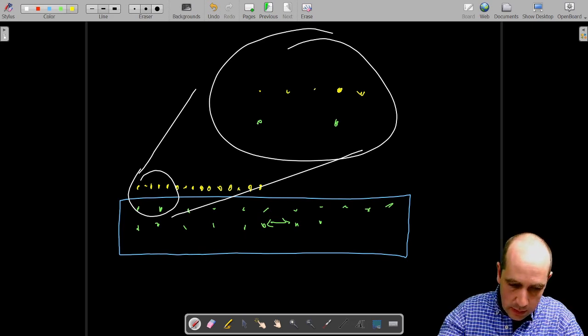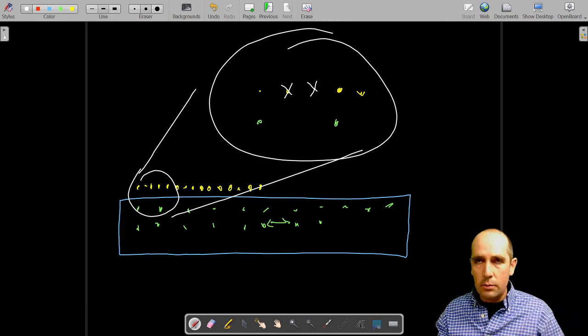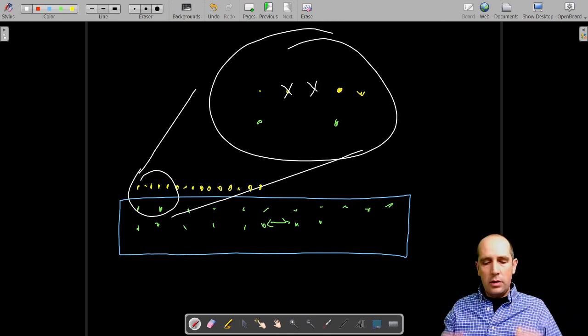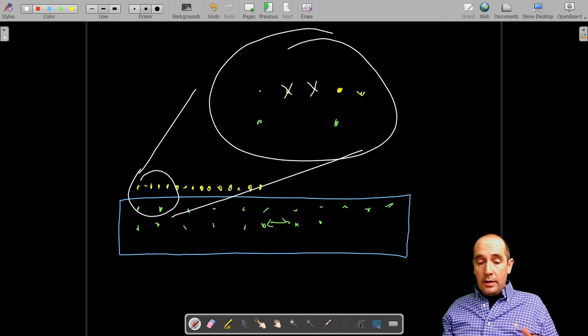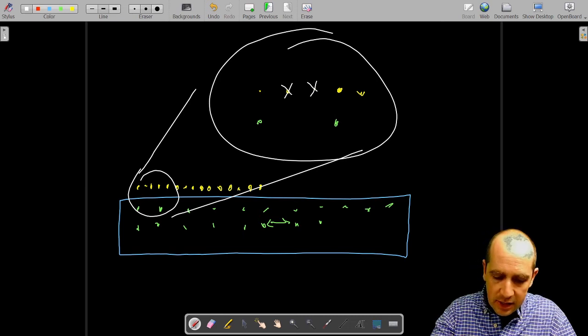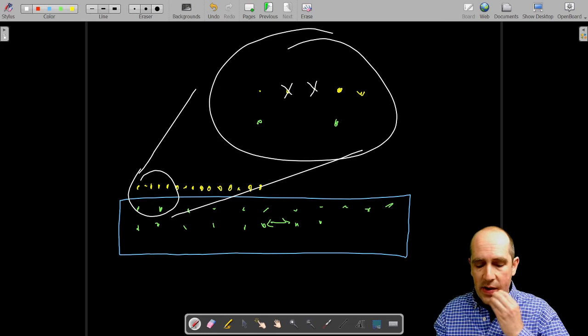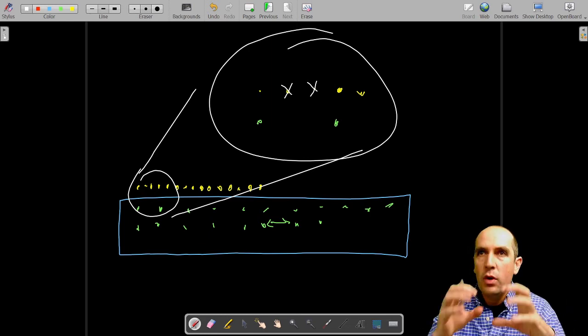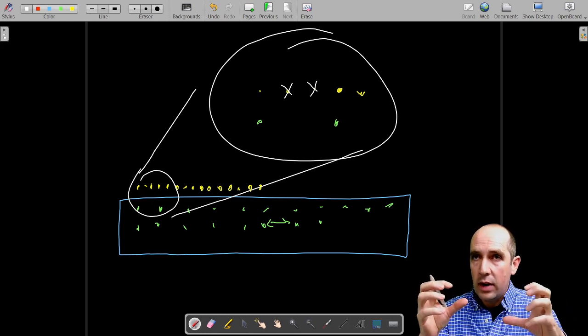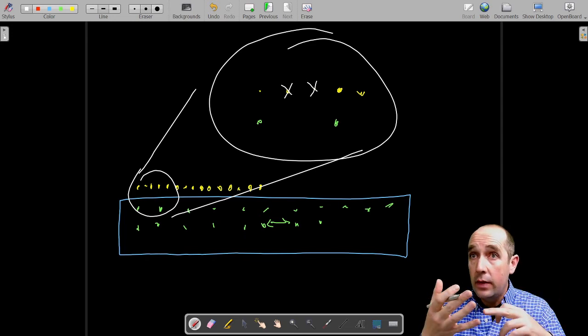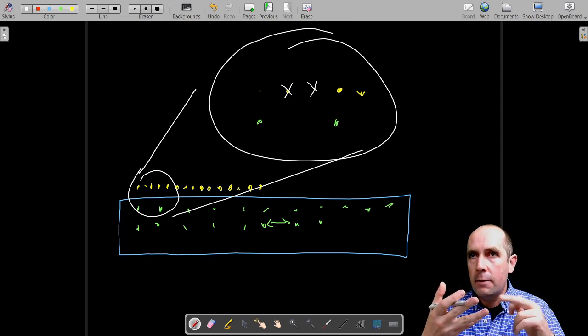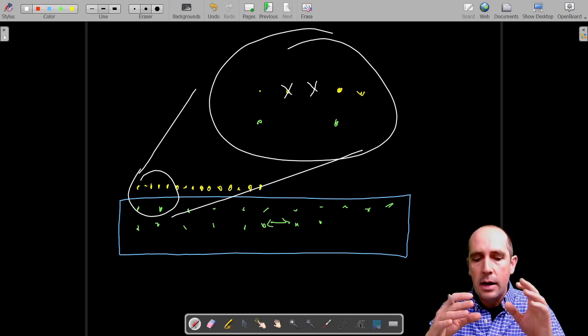So we just find a way of forcing these atoms to align with the silicon or the substrate's lattice. What will happen is that the material that we grow on top, the yellow one, so the germanium or whatever it is, will be stressed. So it will be subjected to stress. This will change, of course, the lattice. This will change the band structure. It will produce also defects and all sorts of different things.